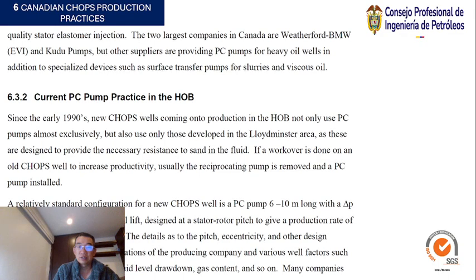The details as to the pitch, eccentricity, and other design parameters depend on the expectations of the producing company and various well factors such as viscosity, expected annular fluid level drawdown, gas content, and so on.